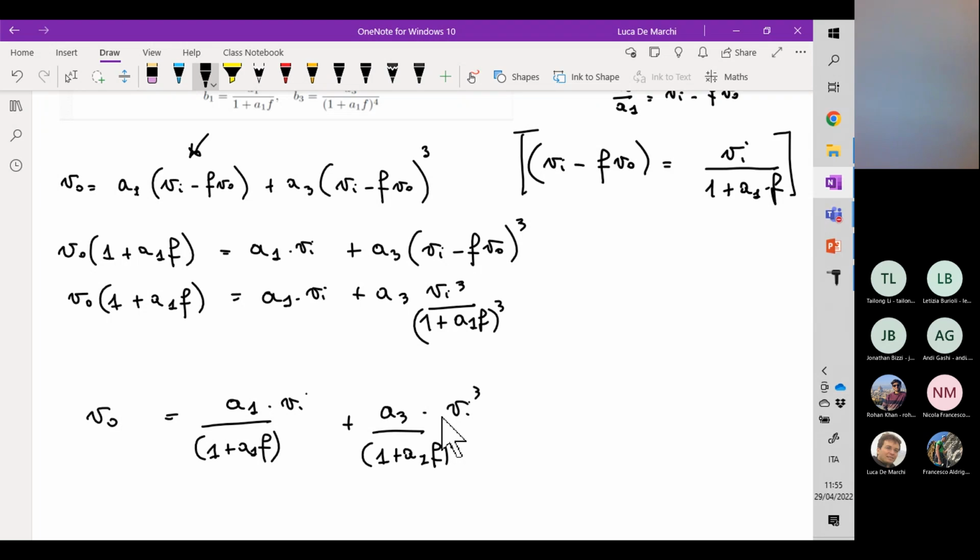Okay, so bandwidth is increased by this factor, and the DC gain is decreased by this factor, but typically this is not an issue because we don't want arbitrarily high gain, we want precise gains controlled by this factor here, 1 over F. Okay, so this is a graphical representation more accurate with respect to what I have sketched in the previous slide.